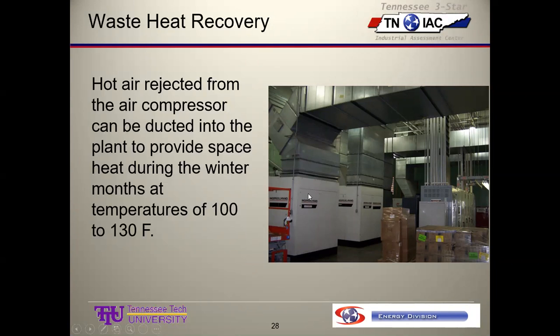The fans in the compressor box can push it a little ways. I think these people had actually put in some additional fans to distribute this heat out, because this was a pretty extensive duct system, which will have some pressure drop on it. So you can push it a little way, like through a wall, with a fan inside the compressor box, but much more than that, then you're going to have so much pressure loss that you're going to reduce the airflow and you're going to have a hard time cooling your compressor properly.